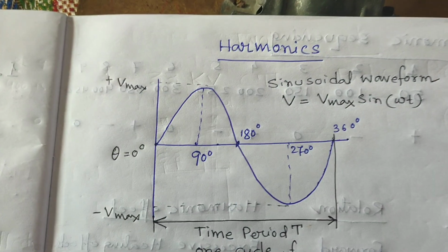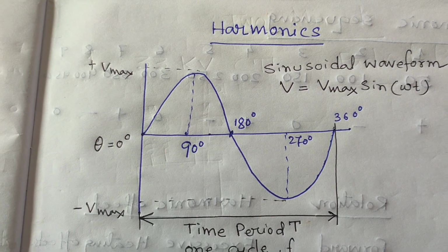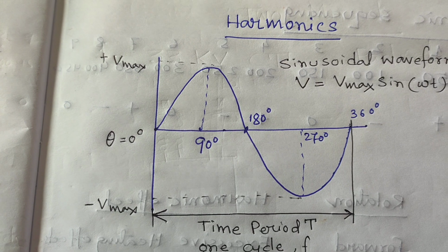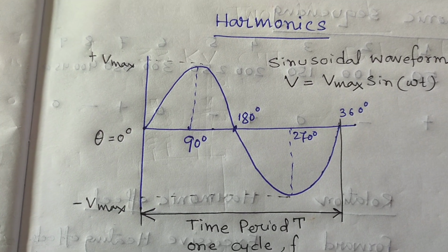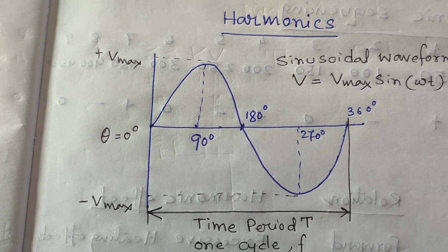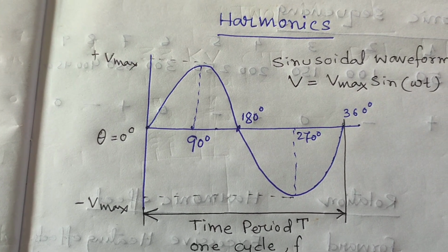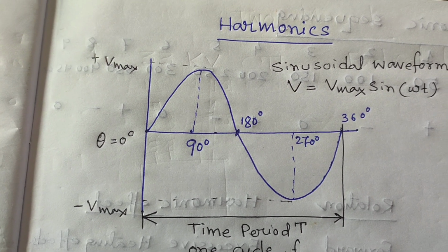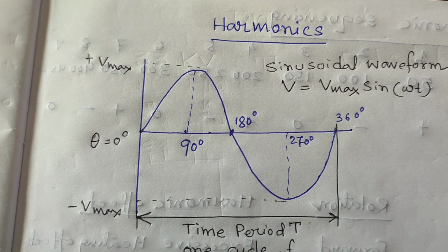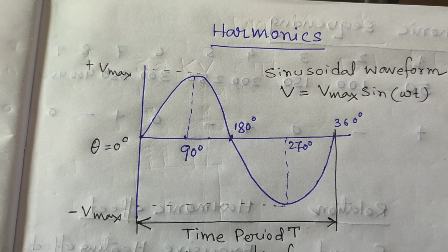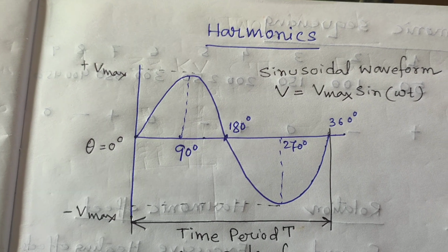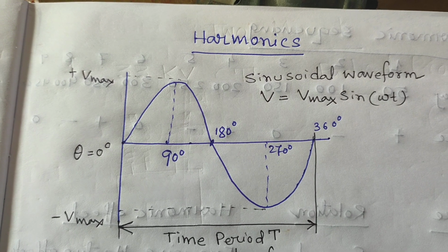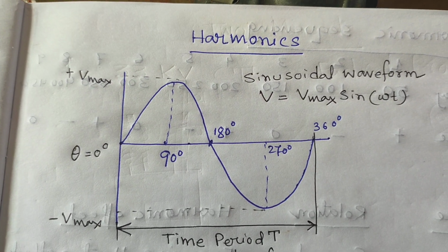Also, most electronic power supply switching circuits, such as rectifiers, silicon controlled rectifiers (SCR), power transistors, power converters and other such solid state switches, cut and chop the sinusoidal power supply waveform to control motor power or to convert the sinusoidal AC supply to DC. This switching circuit tends to draw current only at the peak value of the AC supply, and since the switching current waveform is non-sinusoidal, the resulting load current is said to contain harmonics.